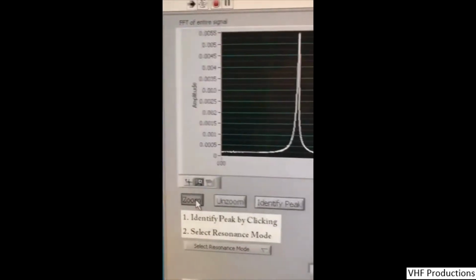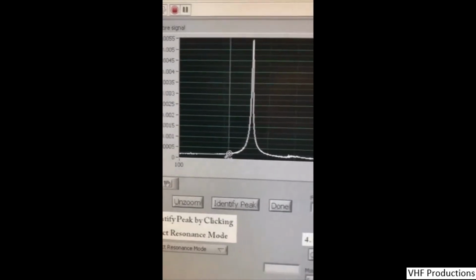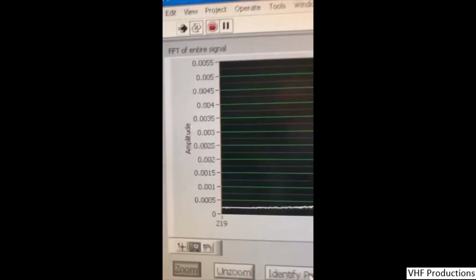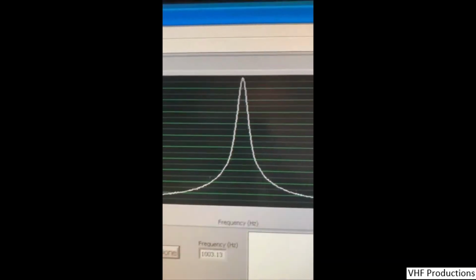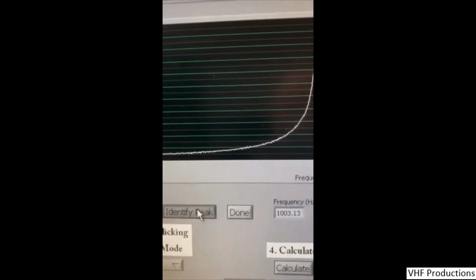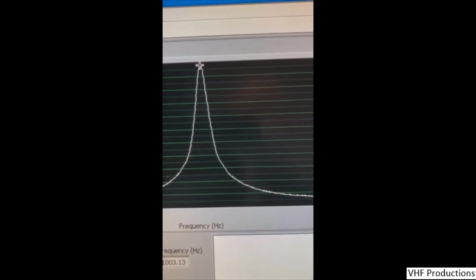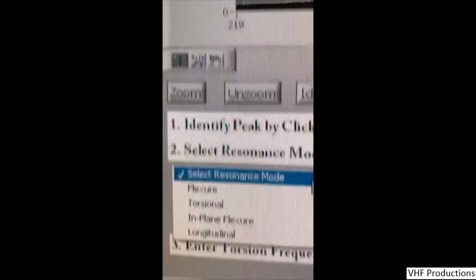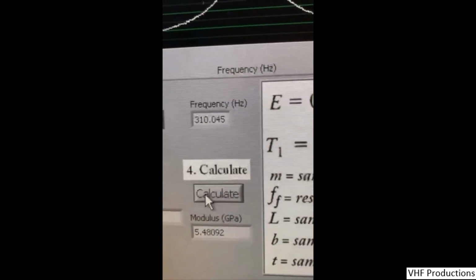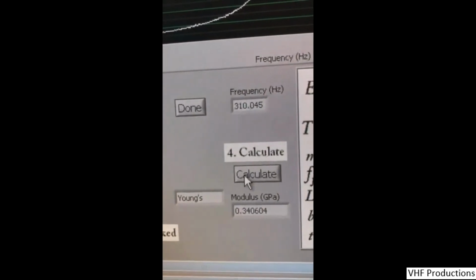We set up the sample on the wire support centered between the two wires and align the microphone on the center of the board. Strike the board at the midpoint along one end and record the acoustic signal. We then apply the Fourier transform to the signal and complete the rest of the analysis.